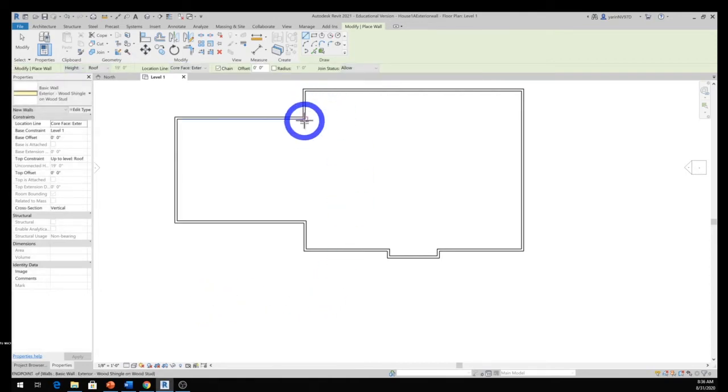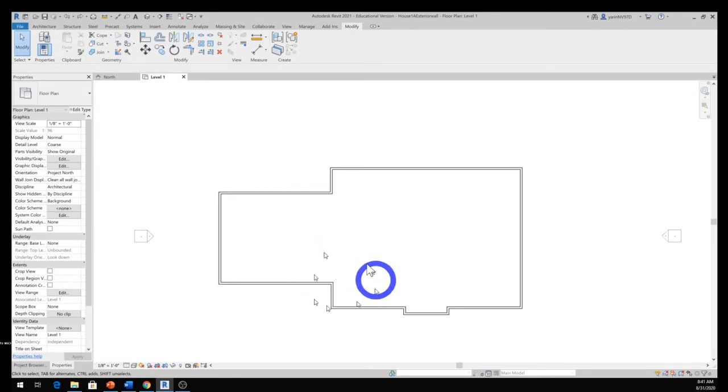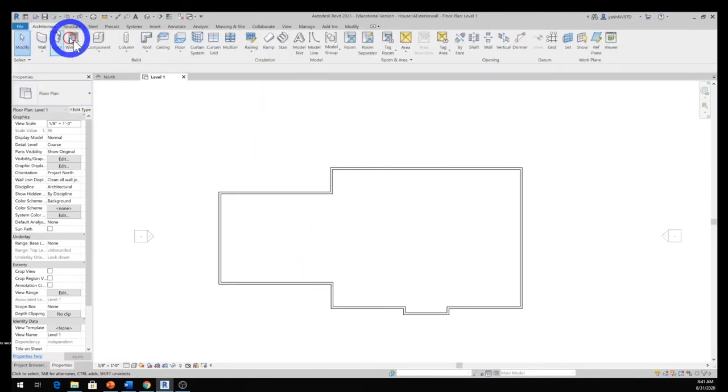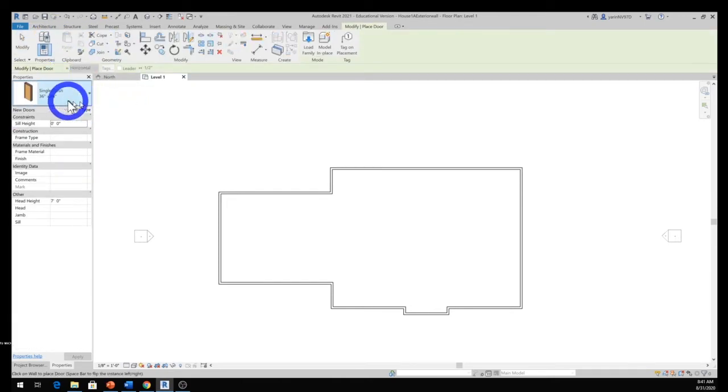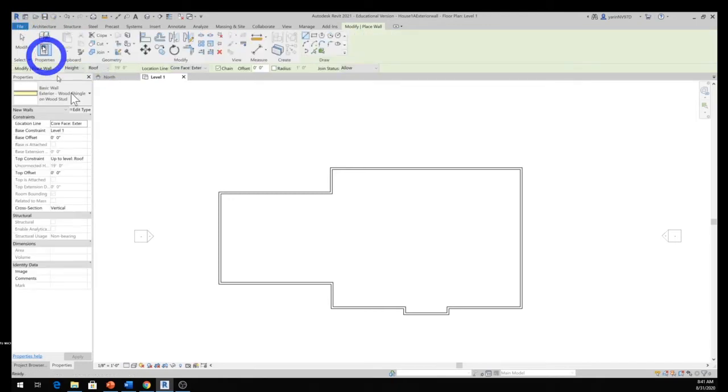Now let's connect these two walls back right here, and maybe we can use the align tool here. I'm going to go ahead and click wall again, and right here, whoops, that's not wall. There we go. Click the wall. Make sure you have the same property right here, height 9, roof. Yeah, that's good.